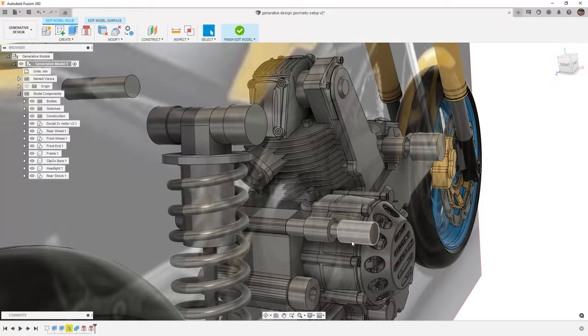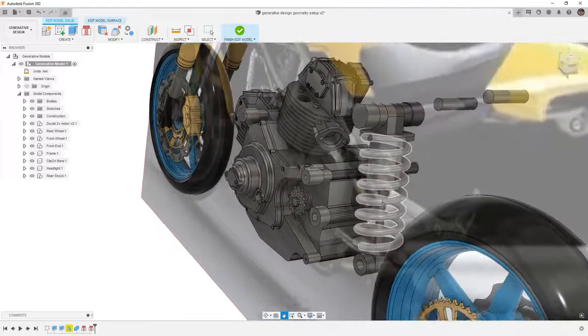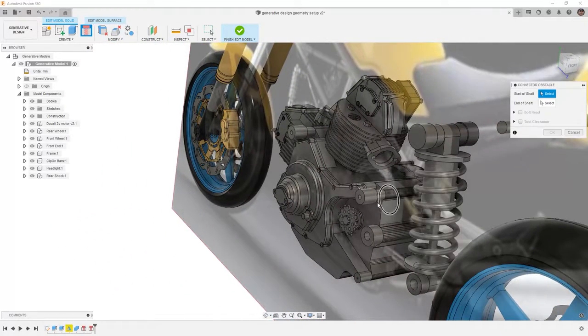This tool is not going to remember our previous settings, and you can see that we have different values for the front and back. What's important to note is what we're really doing here is defining the head of the bolt and how much clearance we actually need to get to it. Keeping in mind that in most cases, if we are going to have a hex bolt, for example, then we would need to make sure that the diameter of the head clearance is large enough to accommodate the tool that we're using. In this case, we're going to be using an Allen key or some sort of Torx, so we don't really need to get all the way around the bolt head. But keep in mind that it is important for us to remember that there are specific instances where we might need to increase these values.